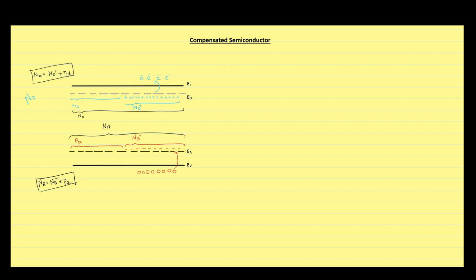These are the electrons which exist as a result of ionization. Similarly, we will assume that there are a few electrons which will be naturally present due to the temperature, and the overall concentration of all these electrons will be equal to N0. Similarly, the holes which we have represented here are the result of ionization, and we also have a few other holes which are caused due to the temperature only, and the net concentration of holes is P0.